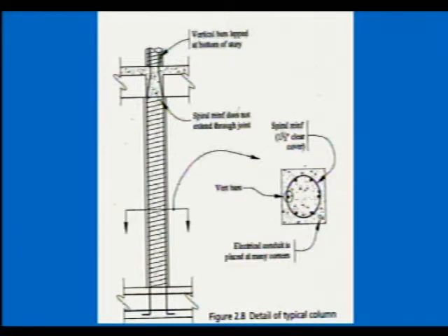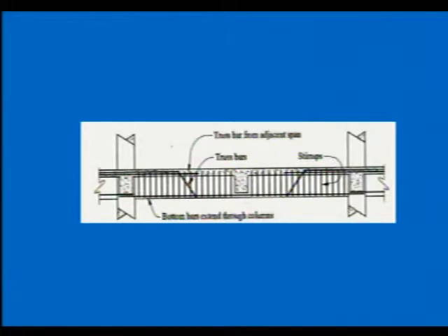Look. Do you know how the Pentagon was built in the 40s? They saw that a war was coming up and they needed a building. But they thought, what were they going to do with this building after the war? It wasn't going to be used for anything, so they built it as a warehouse. Instead of designing it for, say, 300 kilograms per square meter, they designed it for 10 times that, which was good. They also designed the first floor with spiral columns, which was even better because of the toughness of these columns. And they anchored things elegantly. They built this with a code that was only about 50 pages long, but they built a beautiful structure, and the Pentagon did not fail. It didn't kill anybody because of the failure that occurred afterwards.